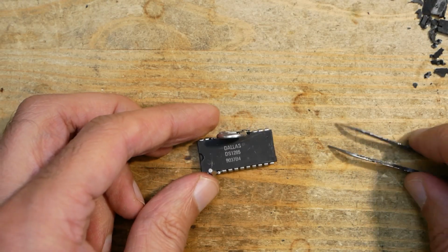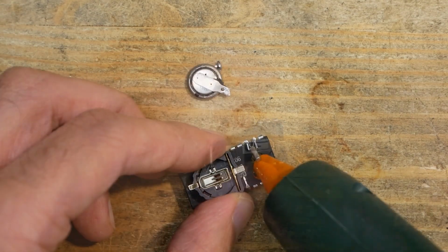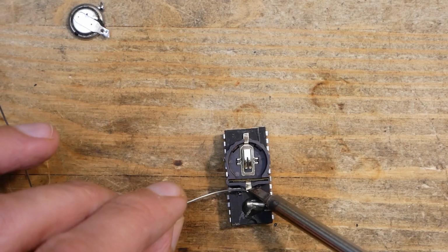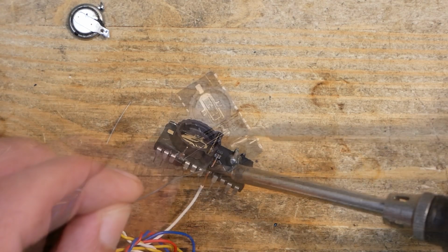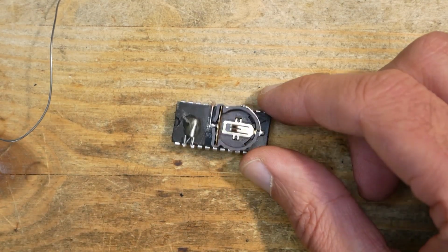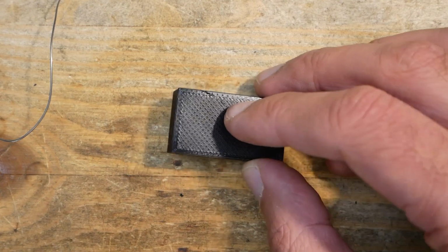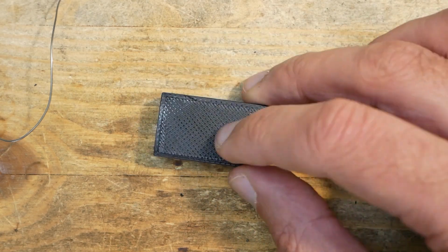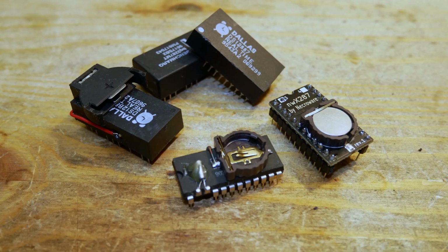On mainboards which don't have a dedicated place for the battery, you can still use the solution with the external battery, or you can remove the case and the resin, solder a battery holder directly onto the pins instead of the old one, fix everything with a bit of hot glue and cover it with a 3D printed case if you like the original look. Just don't glue it again to be able to easily replace the battery later. Lots of new options, and I'm glad that I finally found the time to experiment with it.